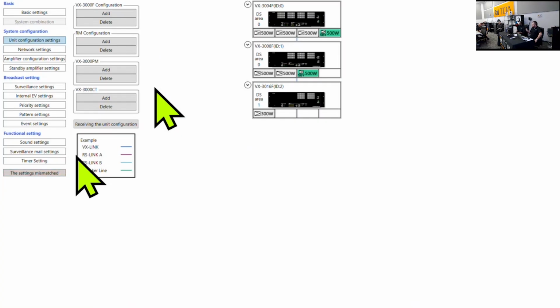So if the system is live and you change the IP address, it will interrupt the broadcast. It'll reboot enough so that it can take it, because the VX itself won't turn itself off completely. It'll just do a light cycle so it can actually use the new IP that you gave it.